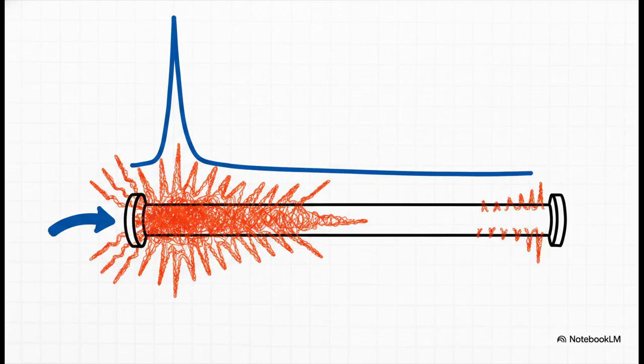Because the thermal boundary layer is still extremely thin right when the fluid enters, the temperature gradient there is incredibly steep. This causes the average Nusselt number to spike massively near the entrance before it slowly drops back down to that steady 3.66. You absolutely must remember this distinction, especially when calculating heat transfer differences for very short pipes.